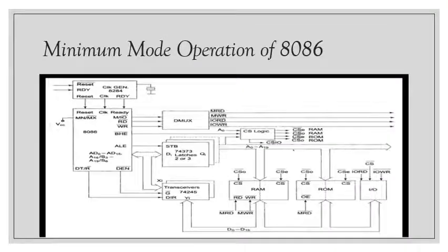Okay, let us start discussing the modes of operation of the 8086. We begin with the minimum mode of operation. In this mode, the microprocessor 8086 is operated by strapping its MN/MX pin to logic 1. In this mode, all the control signals are given out by the microprocessor chip itself. There is a single microprocessor in the minimum mode. The remaining components in the system are latches, transceivers, clock generators, memory and I/O devices.